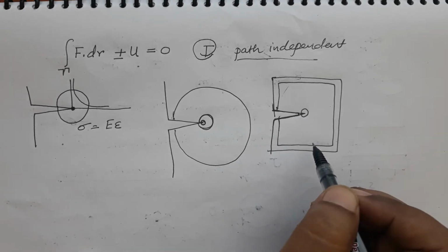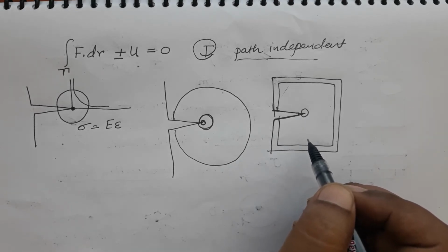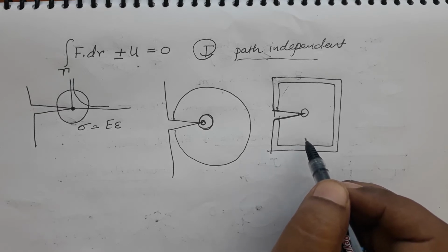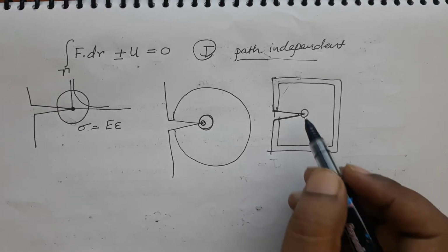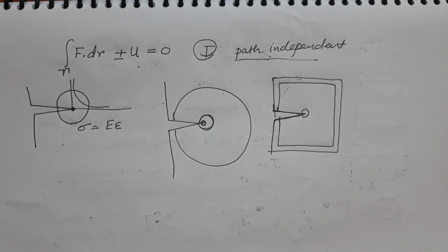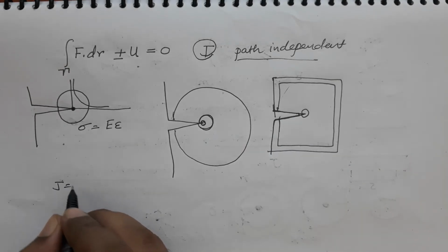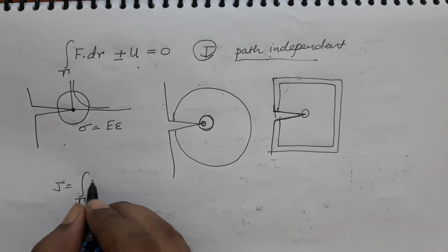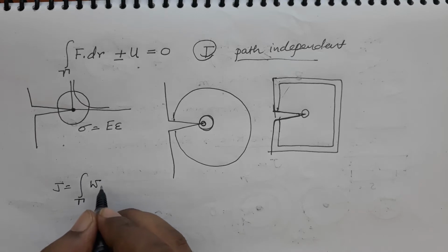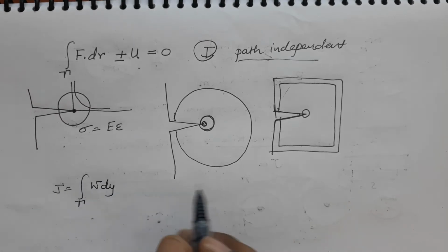This gives us the advantage of doing a test and using this formulation to get the information relevant at the crack tip. If you remember, the J integral had a mathematical description at the crack tip, which was the strain energy density integration along the y direction.